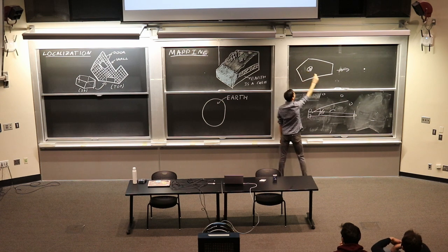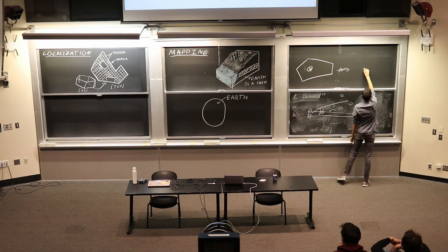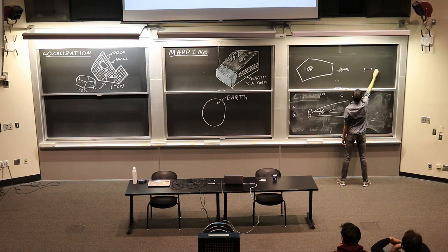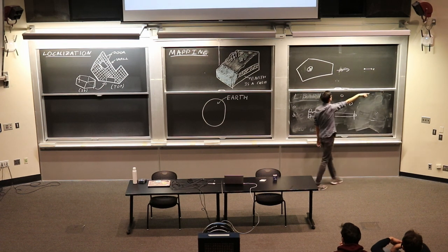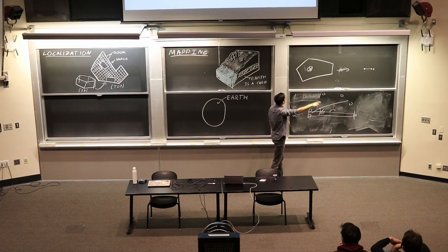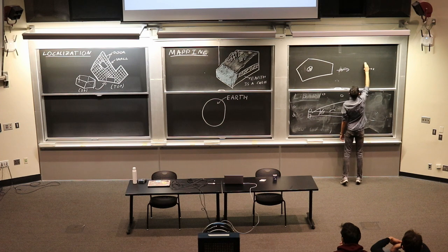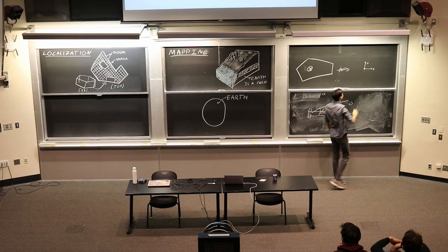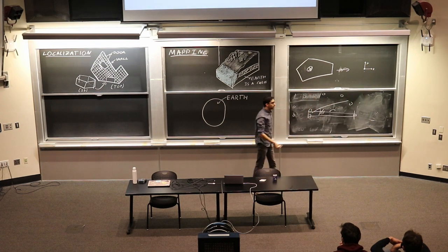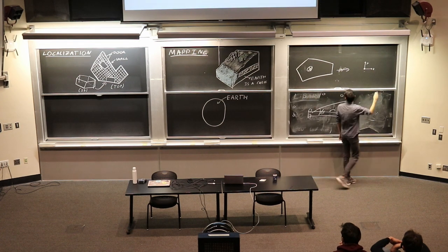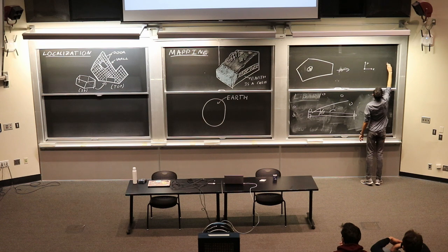That's the origin. My positive x-axis goes in the direction of the front of the LiDAR. My y-axis goes perpendicularly up because z comes out of the page towards me. And my point cloud looks something like this.